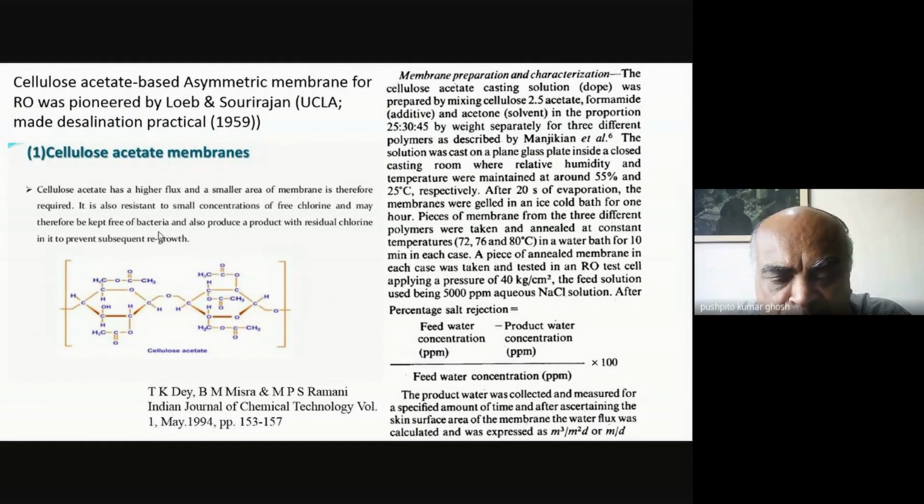And in these particular membranes, what happens is that in the porosity, there is a gradient. So there will be parts of it at one end which will be extremely porous, and as you move towards the other end of the membrane, it gets tighter and tighter. So much so that towards the end, you actually cannot see the pores, but on the other side, you can comfortably see the pores. So this is what it is, and the typical degree of functionalization is around 2, or maybe 2 per sugar, something of that kind.